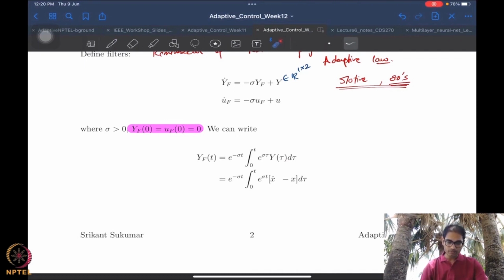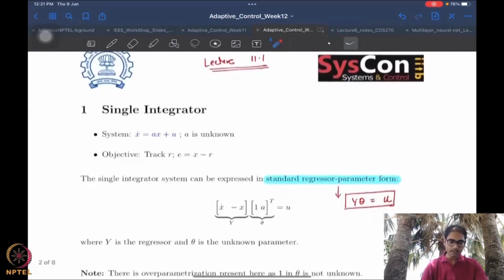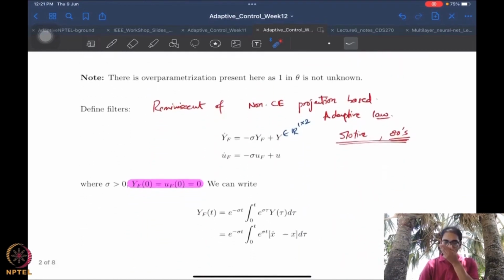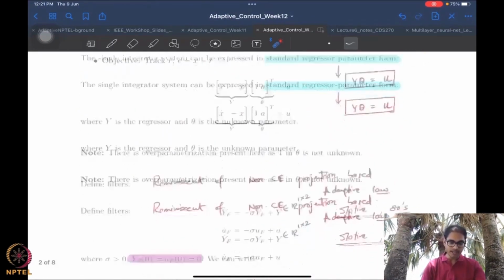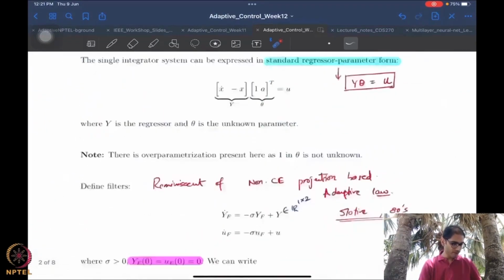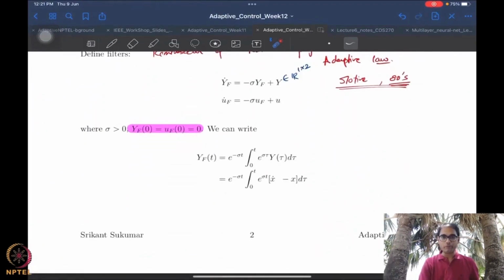All right. So now if you look at this first term here, there's a little bit of a problem. Typically in a state space system, x dot is not measured. You measure the states, but not the derivatives of the states. So this is the typical assumption in a state space system. So the question is, can we still implement this kind of a filter? And the answer is yes. Otherwise, the authors would not have proposed it, I guess.